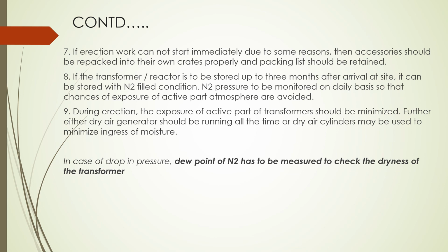During erection, the exposure of active parts of transformer should be minimized. Further, either dry air generator should be running all the time or dry air cylinders may be used to minimize increase of moisture. In case of drop in pressure, dew point of nitrogen has to be measured to check the dryness of the transformer.